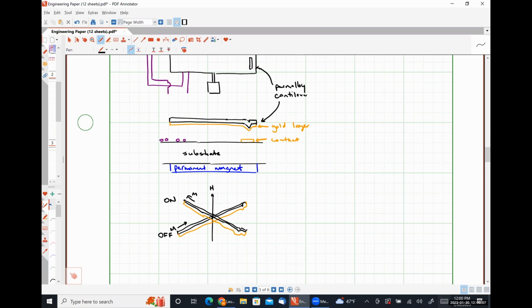One thing that you do have to watch out for, though, and we'll talk about this when we get into electrostatic switching: if you use gold, which is an easily deformable contact material, you can literally stretch it. It's very, very ductile. Repeated switching is going to cause mechanical deformation of your contact and your switch structure. So there's a limited lifetime of the number of switch cycles that you can do with a mechanical switch like this that you won't see in an electrical switch like a transistor, because there's not actual material making contact constantly, hitting each other.